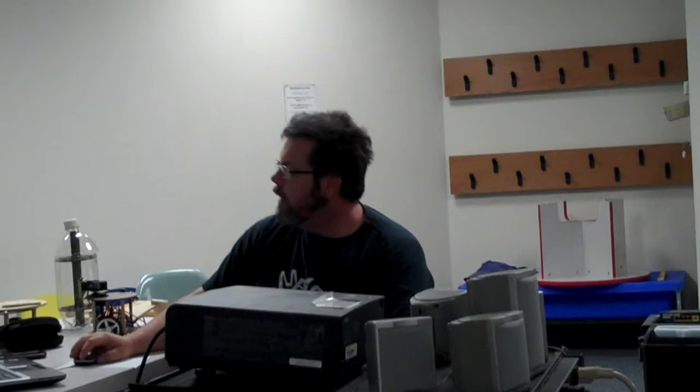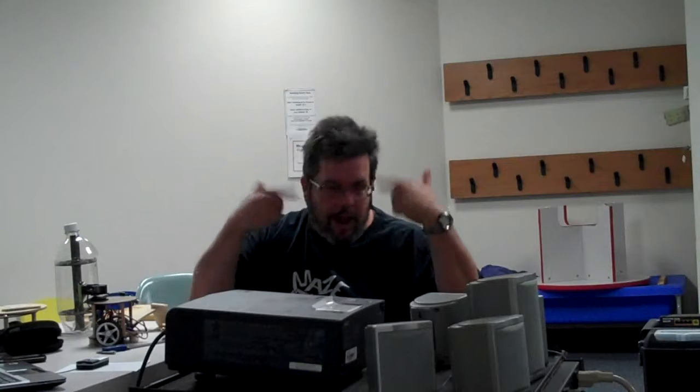I was just curious. Yeah, that's why you always got to keep that origin point in mind. And where does that translate to in ViaCAD? Where does that translate to on your physical machine? Where's your origin point? Because if you lose track of that, suddenly, like I said, it'll be zooming over to the left, and you won't know why, and you'll be pulling your hair out. And so it's kind of a learning process, but it's not that bad. And then once you master or get pretty decent with ViaCAD, then it's just up to your imagination.